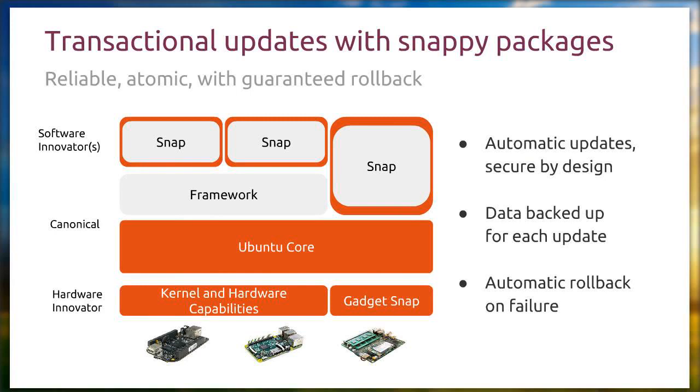You could have the same physical hardware being sold as three independent physical devices in the market. Let's say in one instance, you want the USB ports to be accessible to the end consumers. And on the same device, which is sold as product B, you do not wish the consumers to access the USB ports. So by default, you can blacklist certain kernel modules, in this case the USB kernel drivers, from ever loading in the kernel and essentially create a personality for your device and customize it in a way that is seamless for the operation in that product category.